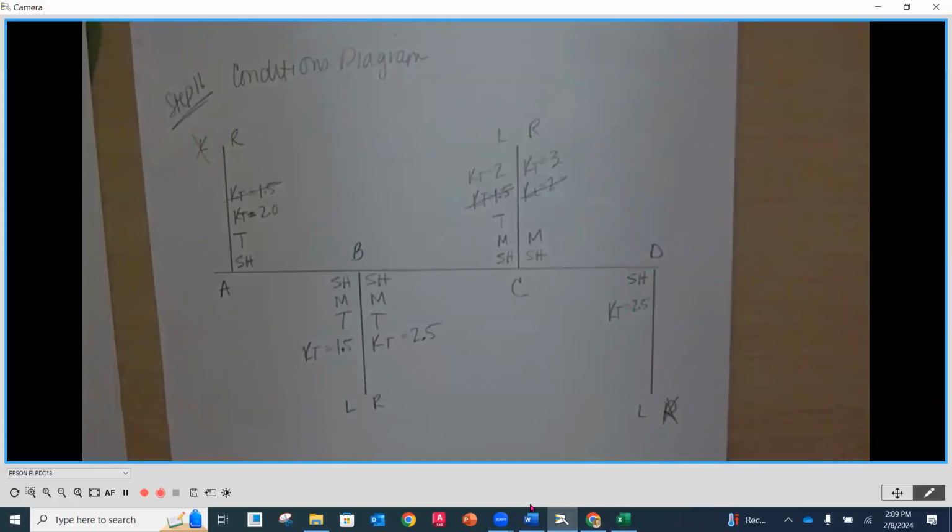So let's go back underneath here. Now, this is the deal with shear. Shear is the one that is going to fail last. We're going to find that when we have shear only, those are going to be our smallest diameters. And whenever it's in combination with something else, it drops out.